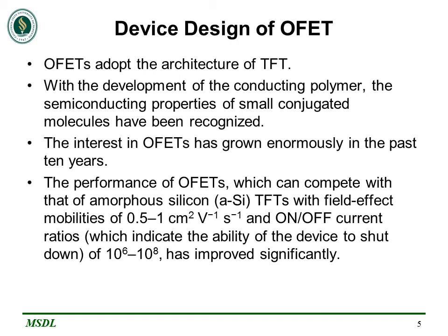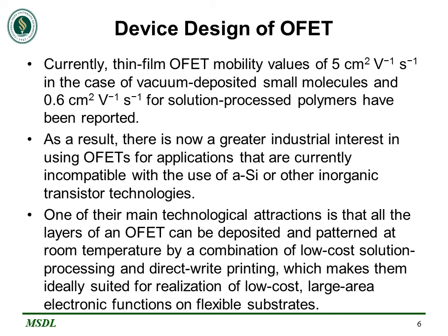With the development of conducting polymers, the semiconducting properties of small conjugated molecules have been recognized. The performance of OFET has improved significantly in terms of on and off current ratio and can compete with the performance of thin film silicon transistors. One main attraction of this technology is that all the layers of an OFET can be deposited and patterned at the room temperature by combining low-cost solution processing and direct write printing.